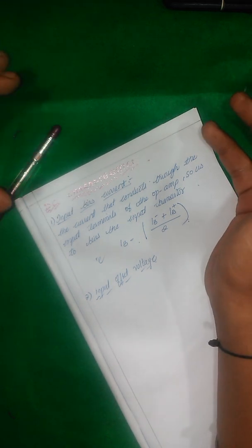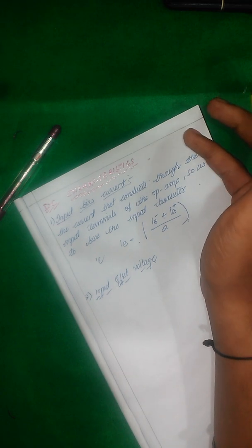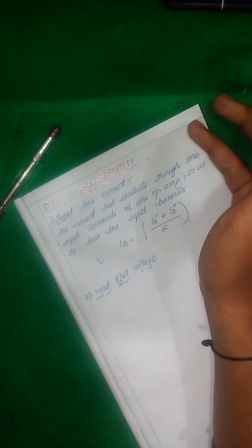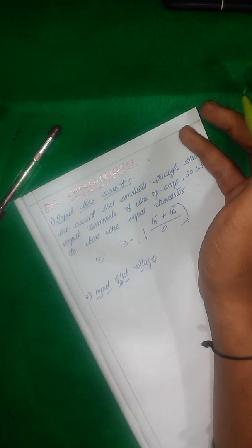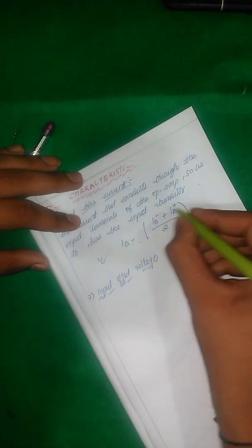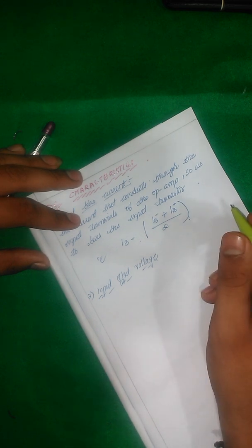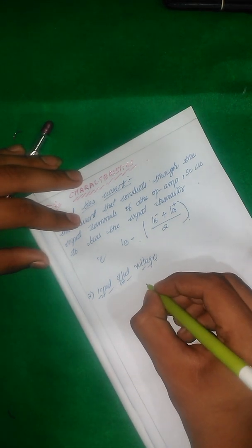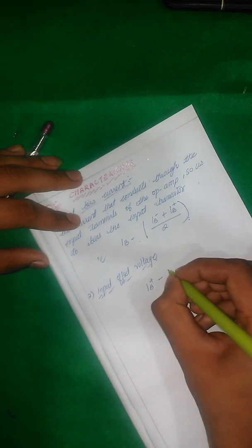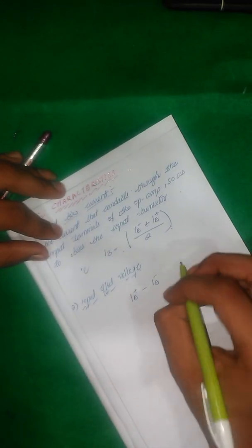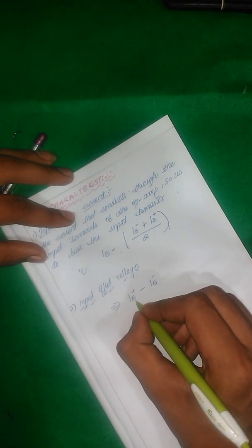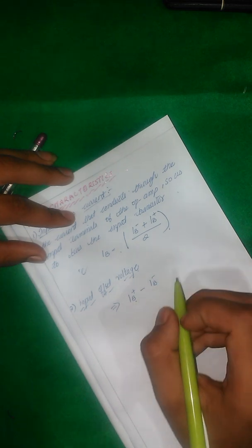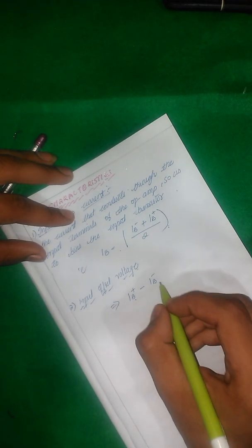They may not be identical, and hence there is a difference in their bias currents. If the currents corresponding to the inverting and non-inverting terminals are I_B minus and I_B plus respectively, then the difference I_B plus minus I_B minus is called input offset current.